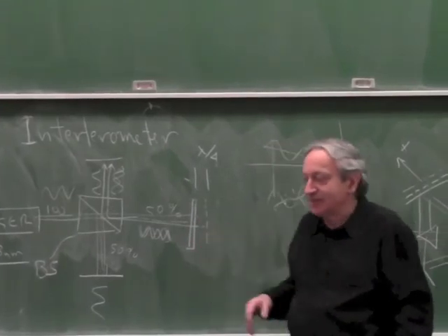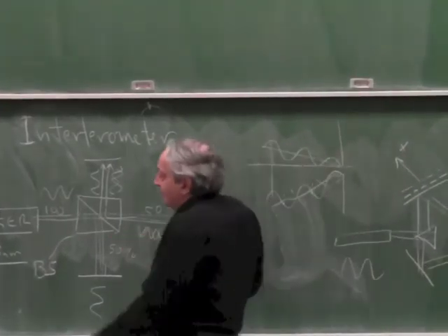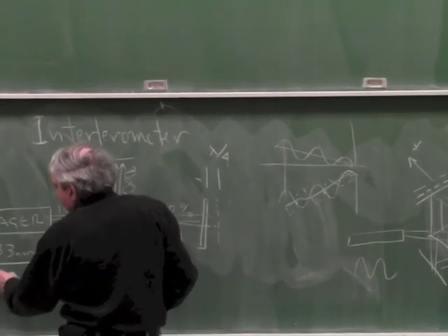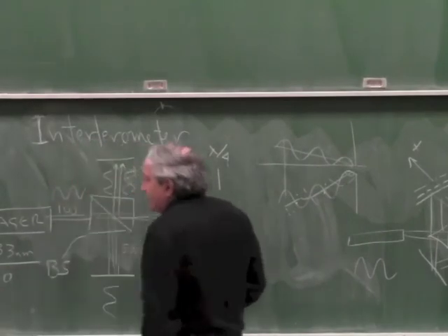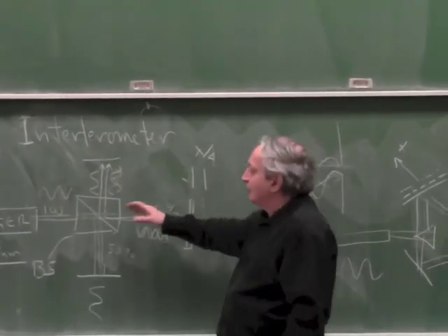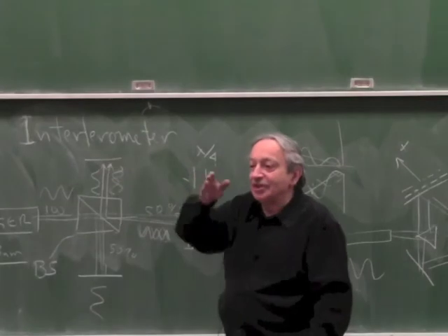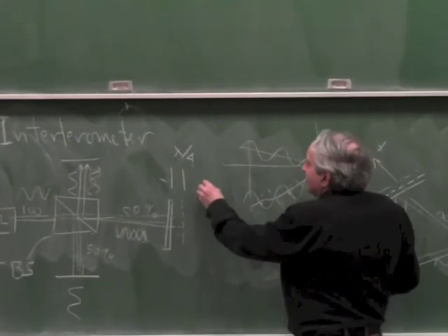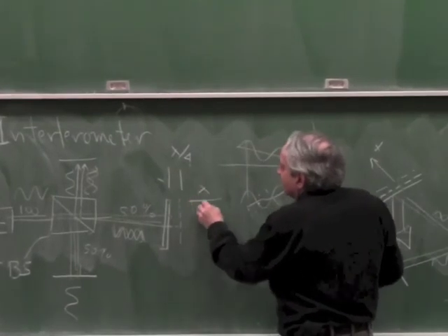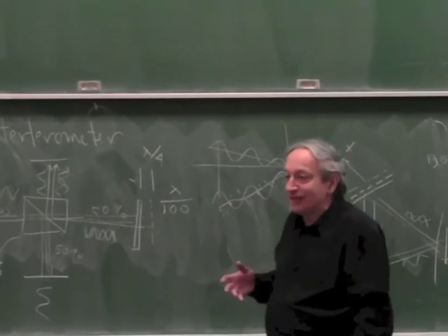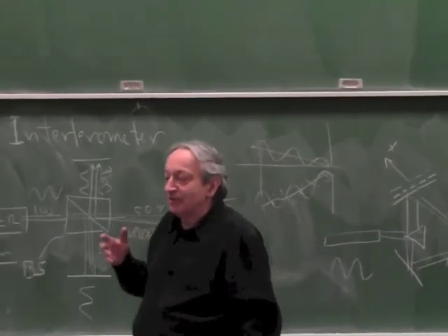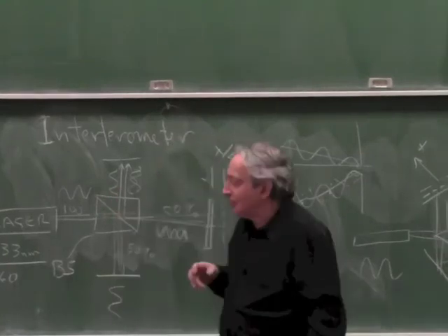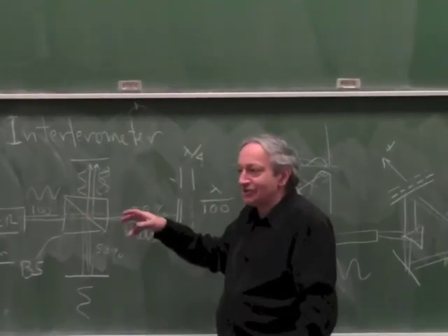You need a very stable laser. So a quarter wavelength of that is roughly 160 nanometers, which will change you from light to dark. But you can interpolate. In the meantime, we get brighter, brighter, darker, darker. So you can interpolate to lambda over 100 easily. So lambda over 100 is 6 nanometers. Most of the high-end interferometers today read out to 1 nanometer. So it's a very, very sensitive device. And you can do all kinds of differential tricks here. You can do a whole slew of tricks.